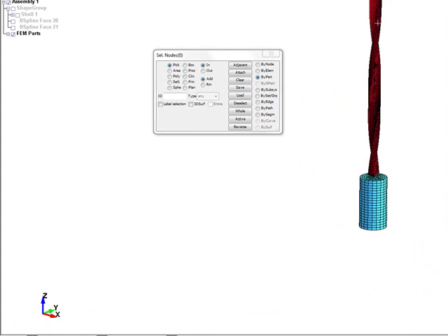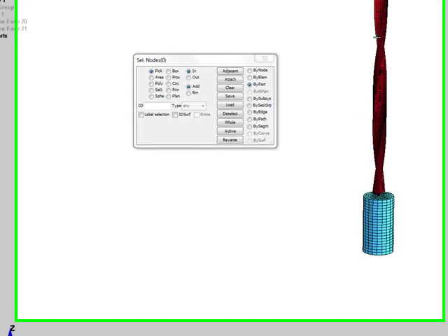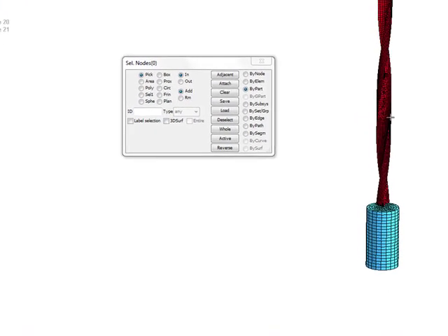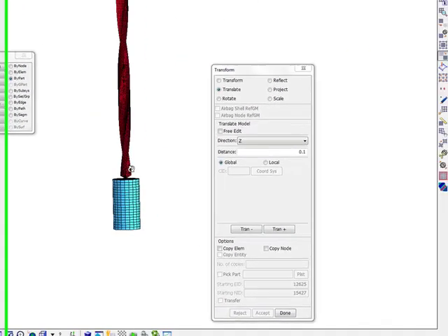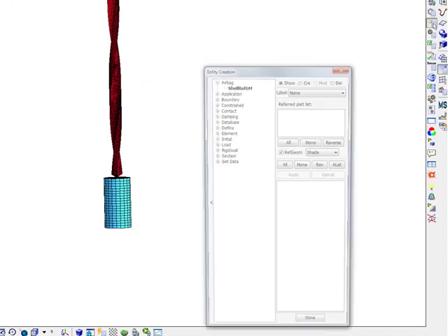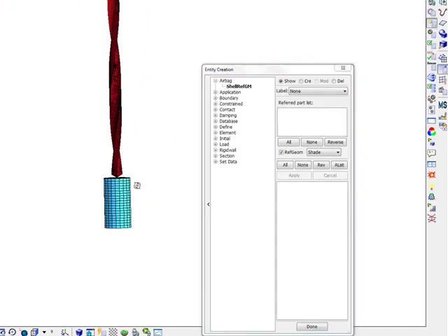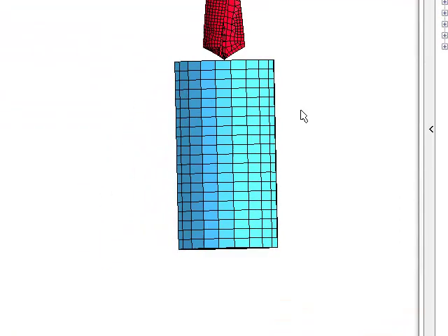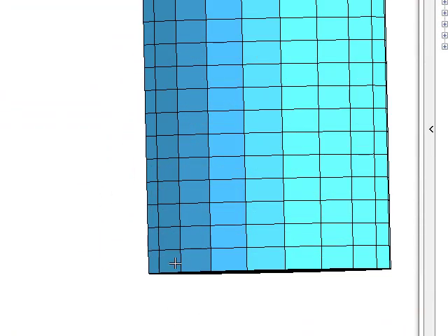The tool is going to rotate around the Z axis, and it is going to move along the Z axis, while the specimen will be fixed in XYZ. Okay, so first we start with a simple thing, how to fix the specimen. We don't want to fix the whole thing. Let's say we just want to fix the bottom here.